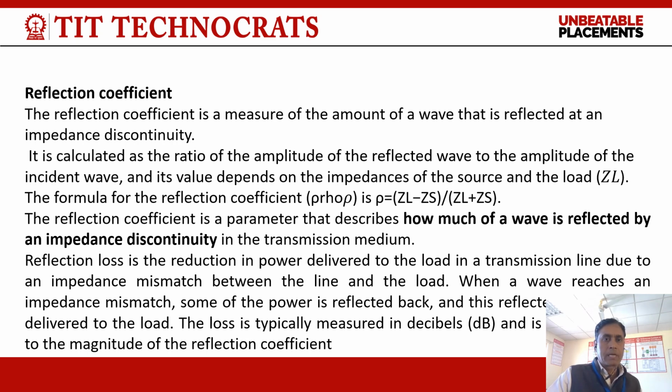Reflection coefficient. The reflection coefficient is a measure of the amount of wave that is reflected at an impedance discontinuity. It is calculated as the ratio of the amplitude of the reflected wave to the amplitude of the incident wave. It describes how much of a wave is reflected by an impedance discontinuity in a transmission medium.